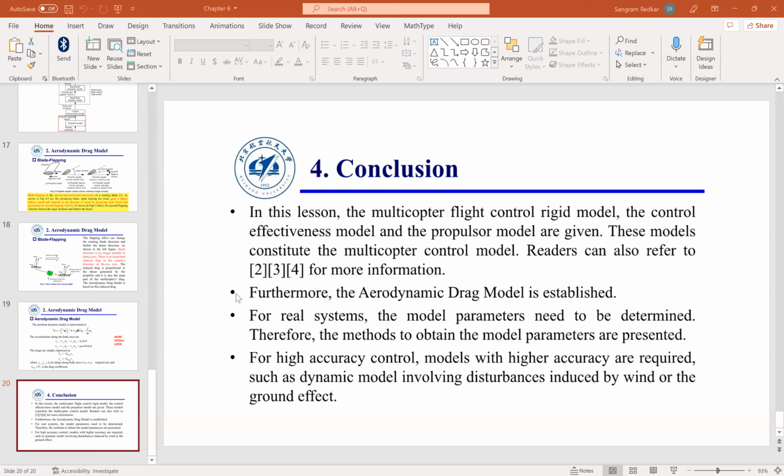That velocity is equal to, on the right hand side, R times VB. What does that mean? VB is the velocity of the aircraft in its body frame. You have this rotation matrix that will take you from body frame to inertial frame, and that gives you Pn dot, Pe dot, and Pd dot. Everyone understood this? So this equation is something like this.